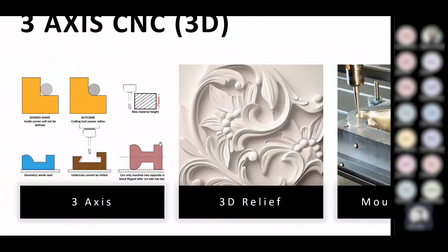If you look at this section over here on the left, you see most of the common issues that you're going to come across. So we already know about this issue here, about things like inner corners due to the diameter of the mill bit. That's going to be a common issue, including going between 3D objects as well. So it's going to kind of round these out instead, so something to be aware of. You're also then limited by the height of the mill bit.